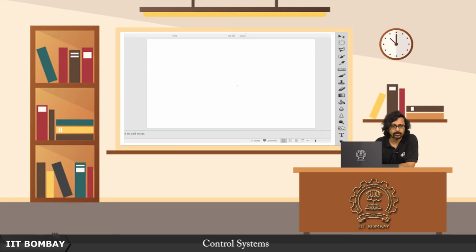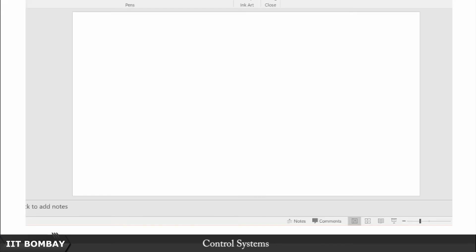Now we are going to see that same system, but now we are going to design an observer. The principle again being, as we have described so often earlier, that if you are not allowed to tap into the system's states, and all that you have access to are the input and the output terminals of the system, we should still be able to design the control action and be able to use some state feedback. So provided the system is observable, we will always be able to design this observer.